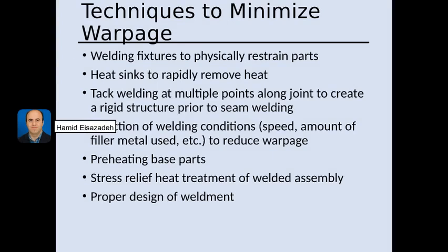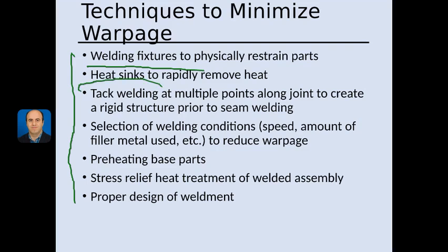Here we have a list of some methods to reduce the warpage. A welding fixture can be applied to reduce the warpage. We can use a heat sink to rapidly remove the heat. We can do some tack welding. Tack welding means you join some points, for example, here we want to connect this interface, right?